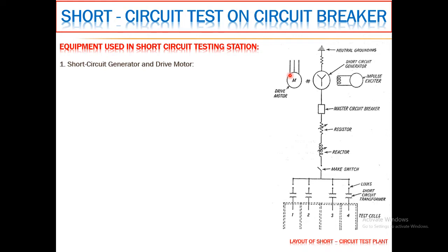In this short circuit testing plant we cannot use turbines, so three-phase induction motors are coupled with the rotor of the short circuit generator.